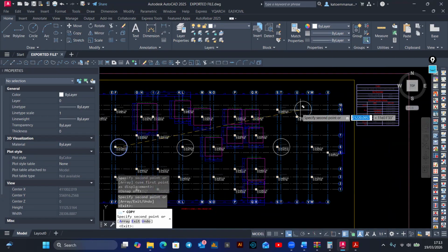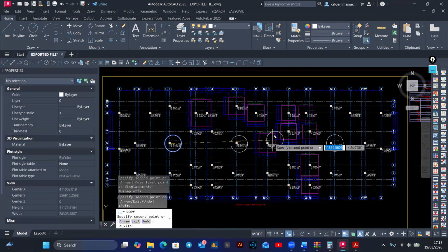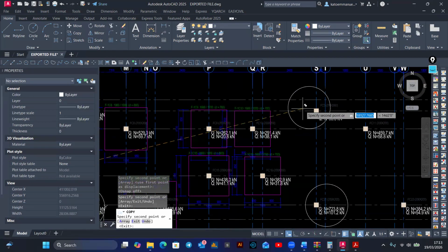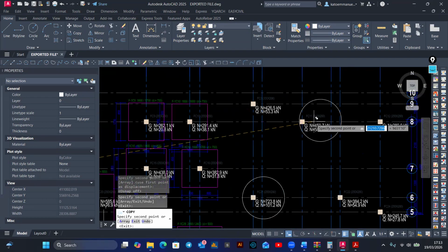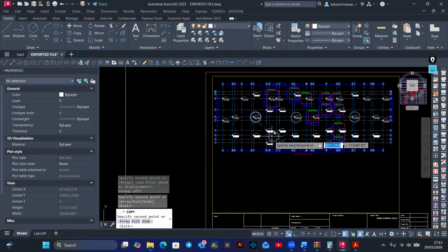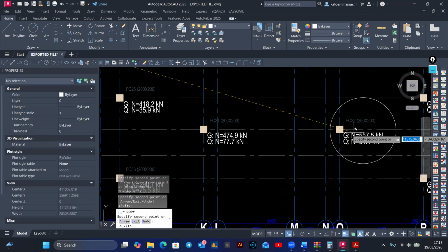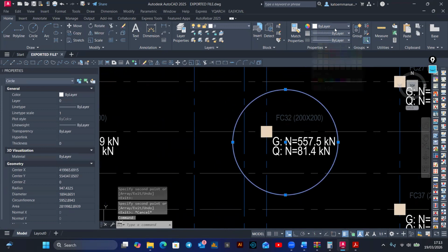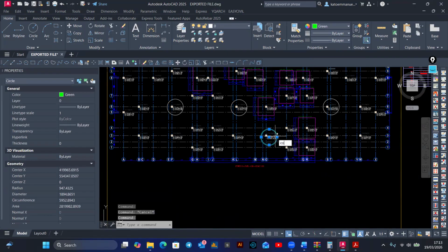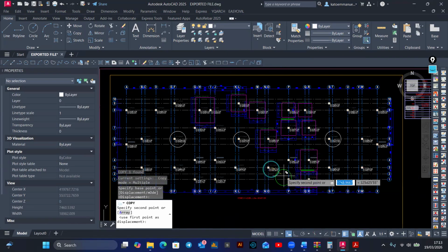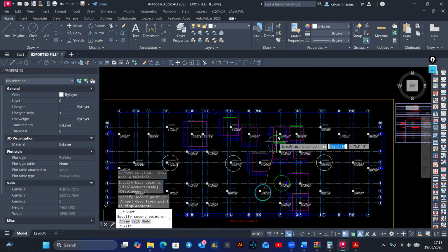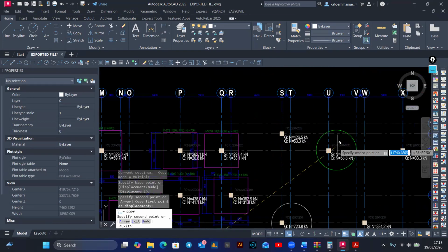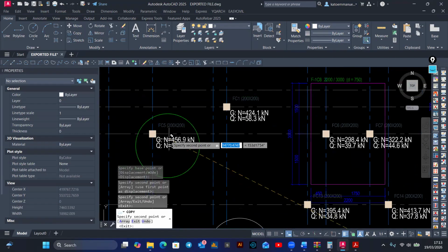Also, maybe the 700s are finished, then you can resort to the 600s. Those columns which have axial loads of 600 and 500, you group them together. For example, I don't have 500 or 600 here, but what is next? Okay, 500 is here. I can group this one and give it a different color, green. That is footing F2. So this footing F2 is going to be the same as this one, which is at 407. It's going to be the same as this.